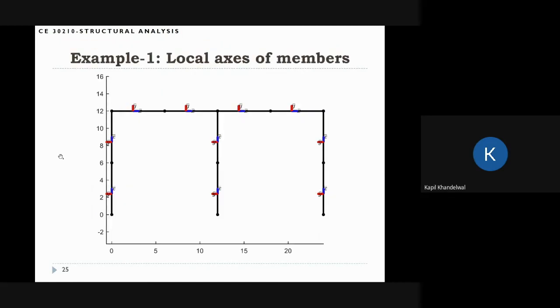I'm again showing you the local X and local Y axes. Because the member loads are now acting on these two beam members, and you can see that Q was acting in the negative Y direction, Q is fine. So we can just use the Q value of 2. We don't have to flip the sign of Q, because that's a positive direction. And we can solve the system.